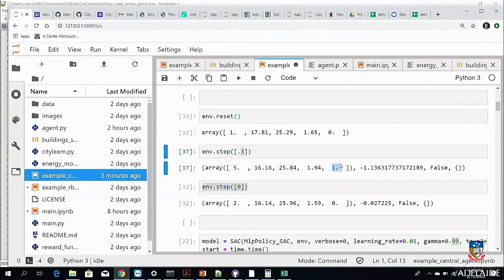So for example here, the state of charge is set at 100%. In this case, the storage device is sized at 3 times the maximum cooling demand for a given hour of the building. So in the summer, the worst energy demand of the building might be, let's say, 20 kilowatts. Then the size of the storage for cooling will be sized at 3 times the 20 kilowatt hours. So let's say that now we take a negative.